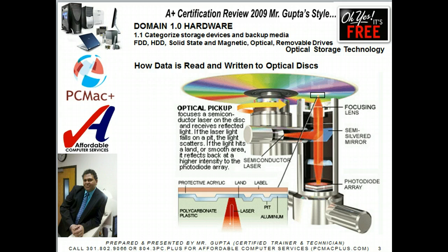The recording begins with the laser making small pits, or tiny indentations, on the dye surface of the disk. The heat of the laser burns each pit through a chemical reaction, causing it to become opaque. This pit will then reflect less light than the areas not heated by the laser.